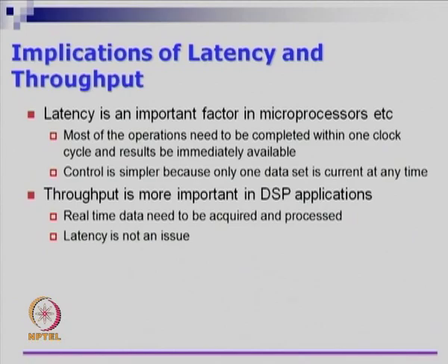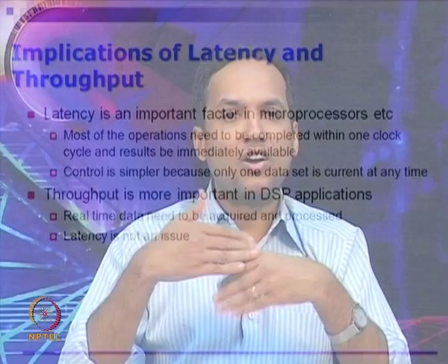So, which means you have to design a circuit that is really fast. Remember, if you are giving only 1 cycle to do addition or multiplication, then we cannot say I will pipeline it and I will get the results after 5 cycles. We need the result in 1 cycle, the whole thing should be combinational and it should be fast enough to accommodate, let us say, 1 nanosecond delay. That is all you can get for a 1 gigahertz clock that is used for a processor. In fact, if you are using a 3 gigahertz or a 4 gigahertz processor, you are looking at either 0.33 nanoseconds or 0.25 nanoseconds to implement the whole adder, or multiplier and whatnot.